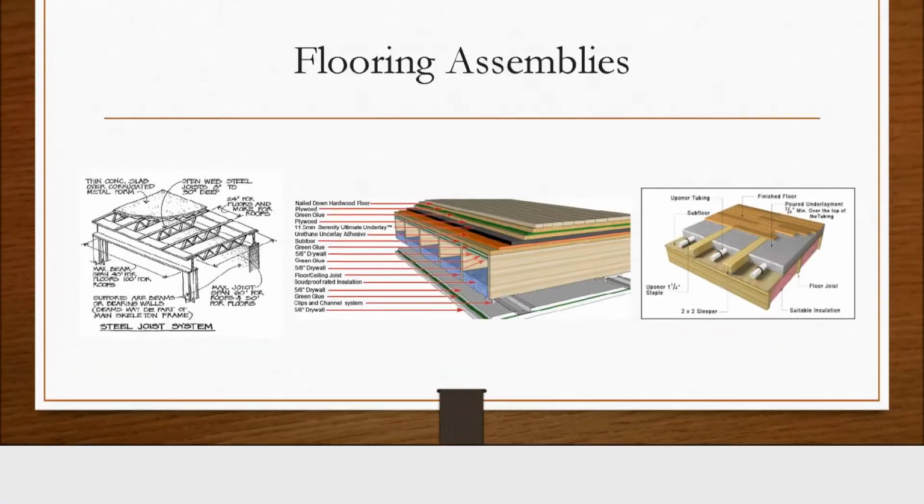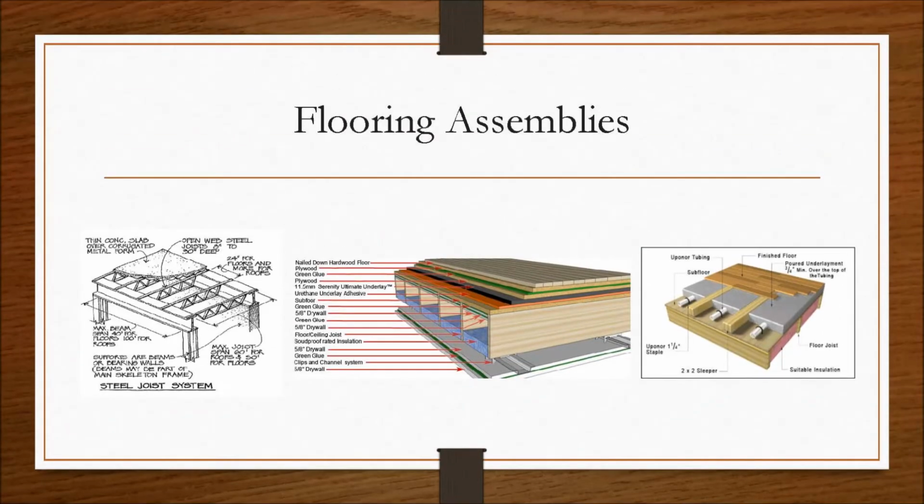A floor must be designed to withstand the use intended for that specific space. Floor systems fall into two general categories. 1. A series of linear beams and joists topped with a plan of sheathing. And 2. Decking or a slab of reinforced concrete.